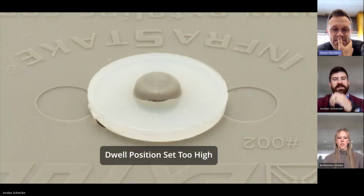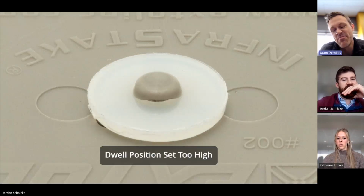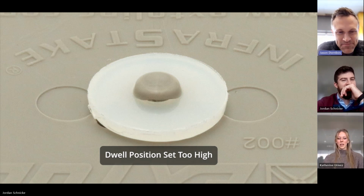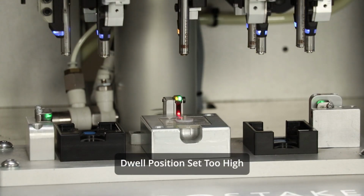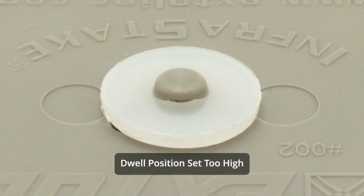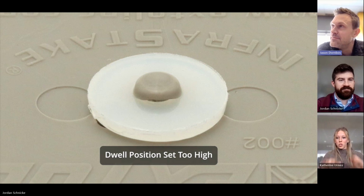Video time, isn't it? Yes. So, I'm very proud of these videos. This video, if you want to push play on that, is just a normal cycle, but your dwell position is set too high. That's the kind of sign that Jordan was talking about, where you take a look at your stake after it's completed. What do you see? This one is not fully filled. You can see that there's a gap between the dome of the stake head and the mating component.